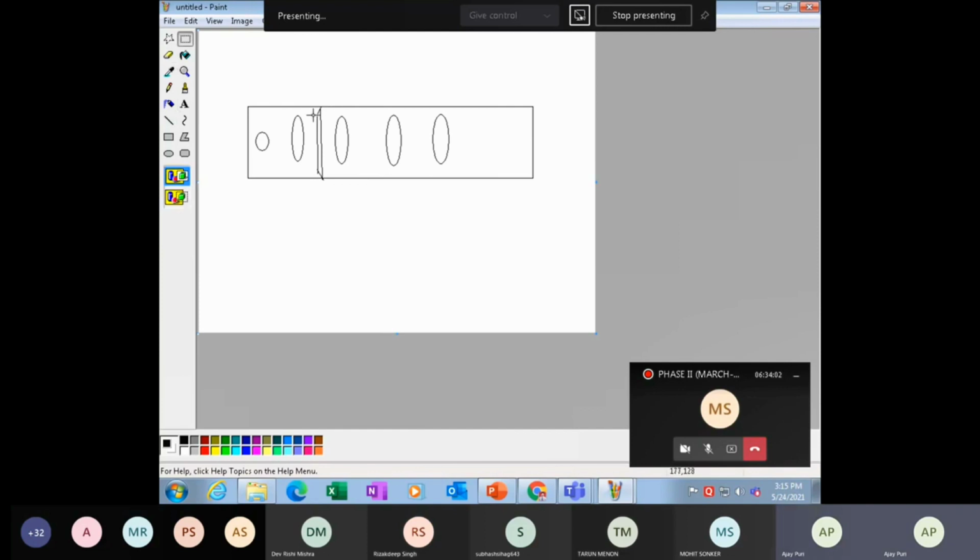Now how will we project it? To project it, we have to have a hidden line. That means we make dotted lines here. That is a hidden line. This dotted line shows that a structure is behind this, so the stiffener is behind this. That is a hidden line.